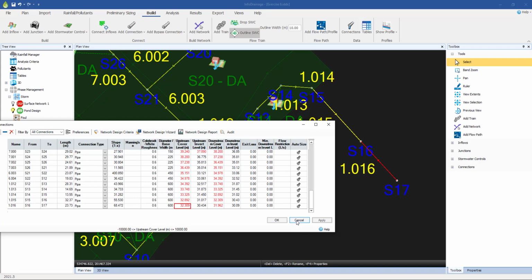And as well, we know the side slope. If you've completed exercise 5, you'll know that we arrived at a Q-bar value in this case, this very UK design-centric design criteria. However, wherever it came from, there's going to be some limit of discharge. And in this exercise, we're going to use a limit of discharge of 16.1 litres a second.